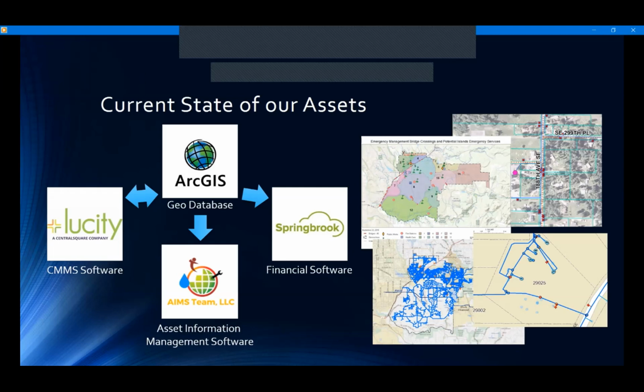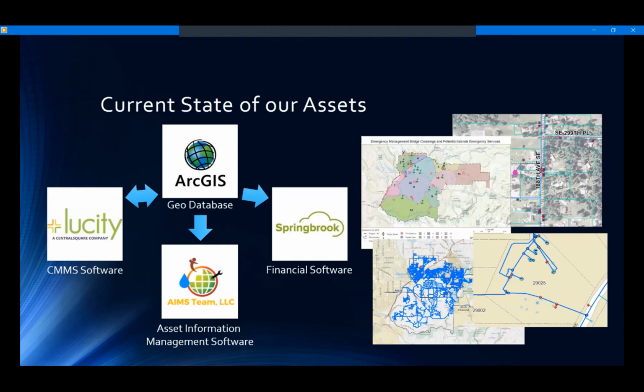And fast forward to today, the district is in relative maintenance mode with this new geodata that's coming in, because it's mostly coming in through developer extensions and capital projects. But this data is captured by our engineering department during construction inspection, and then it's QA/QC'd by our GIS team prior to pushing it into our software packages and updating our asset register. And that has really helped with the data workflows.